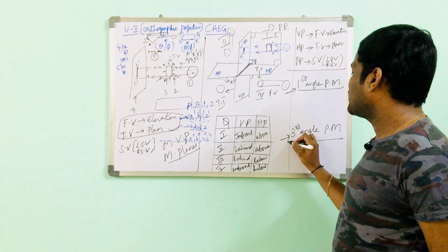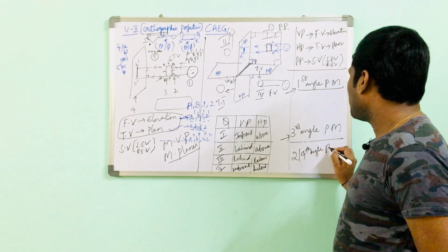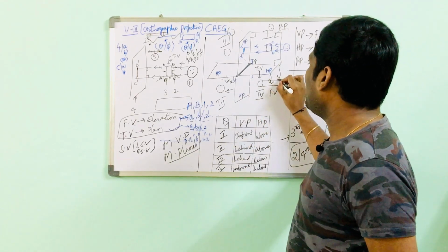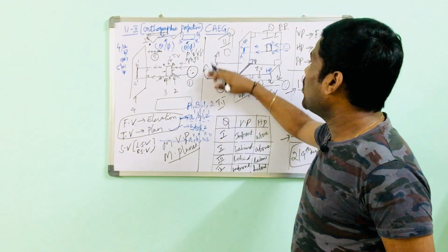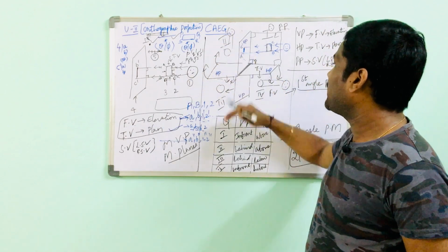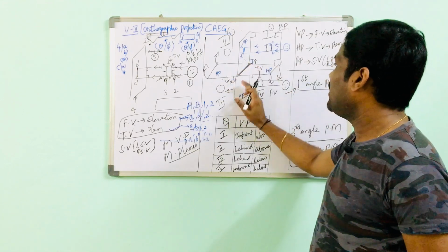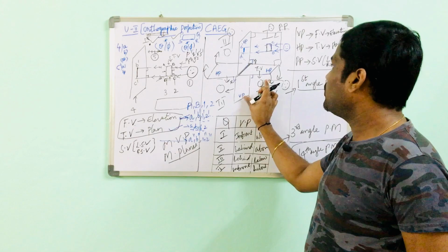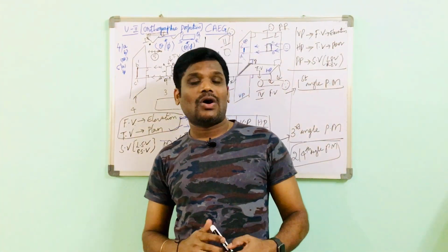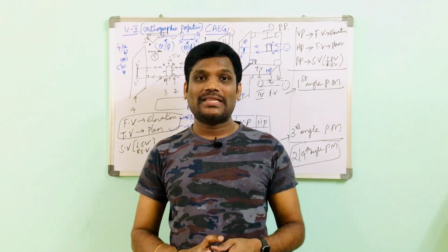What are the first and third angles, and why are the second and fourth angles eliminated from our study? Second and fourth are eliminated because they overlap. When I tilt this plane for the second quadrant, it will be overlapping, and when this is tilted to make it vertical with respect to this plane, this also closes. The fourth quadrant and second quadrant are overlapping, so there is no use in working out the diagrams. So we are going to eliminate the second and fourth angle projection methods, dear students.